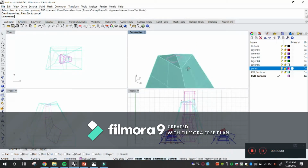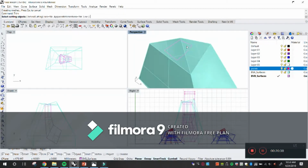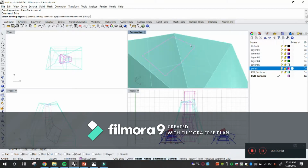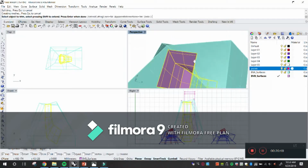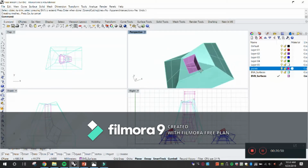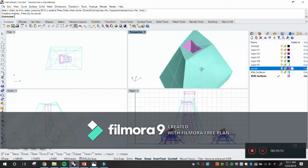Right, so right click. Okay, now what does that allow me? Well, I can type trim again. Now the cutting object would be the purple, right? And then let's see if I can remove this green top right here. Right, ta-da, now I can look inside. Right, now I have that right there. Mind blown.